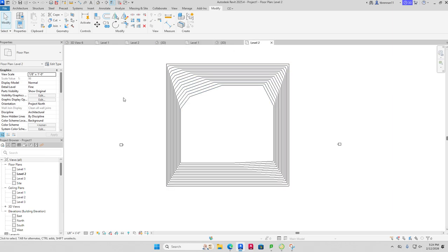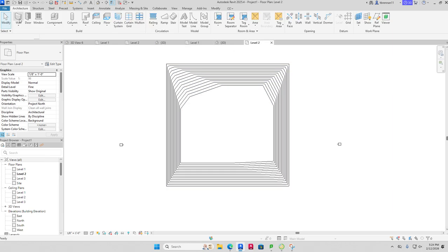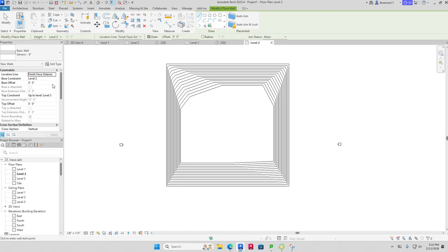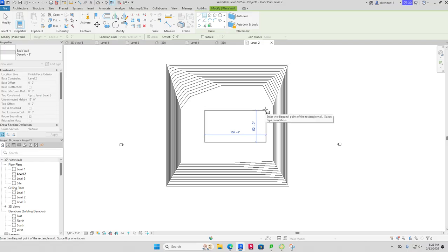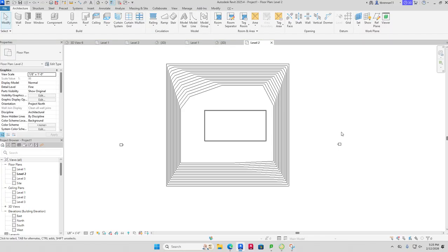over here, I'm going to go ahead and put that in. So I've got this, the wall, generic. Okay, we're good to go. Now I'm going to make a rectangle, and I'm going to make it 100 feet by 50 feet. So I'm going to click here and pick 2 points. Click here, and we'll go like that. Now, what we said before is we want it to be 100 feet by 50 feet, and it is. And then I've got that in place.